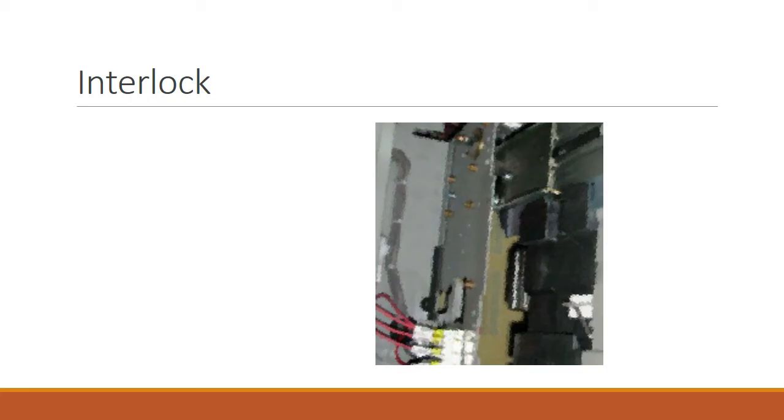Each switch, 3 in total, has a mechanical interlock that locks the switch in the open position when the key is released. The key combination for each interlock is the same. The bus tie switch can't be closed if both feeder switches are closed, since only 2 keys are needed.